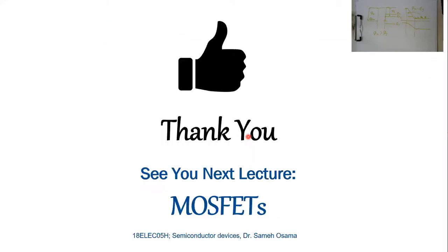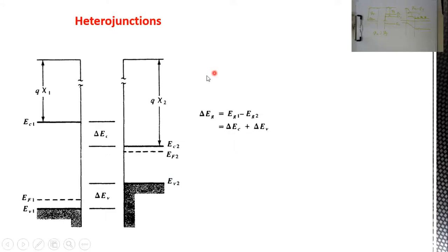Then basically, these two materials will have two different energy band diagrams, and also two different energy gaps, as you can see. This is easily observed here. Again, under thermodynamic equilibrium, you have to have both Fermi levels horizontally aligned. So whenever you start plotting this energy band diagram, you start with a horizontal Fermi level and plot everything with respect to it. But the problem is in continuity. So let's see this problem. Let's try to do this example together.